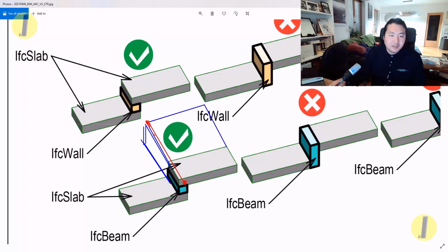In this case, if the span is long, at some point there is no connection with your analytical surface of the floor. So even though you give a coupling connection between this node point and the slab below, the result in the middle here, in the long span, may not be correct.